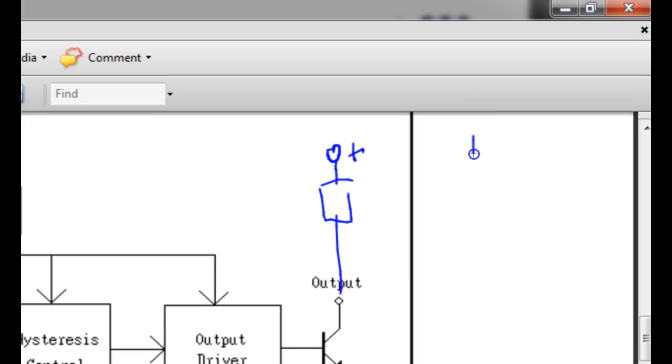So what I have connected up here is a resistor, and then something we haven't got to yet, which we're going to talk about: a light emitting diode. Most people call them LEDs. Have you heard that term before? We put it in there forward biased to make it emit light. I'm going to have to put a power supply up here, but what's nice is the sensor doesn't care, so I'm just going to use plus 5 volts. Then we'll talk about how to size the resistor.